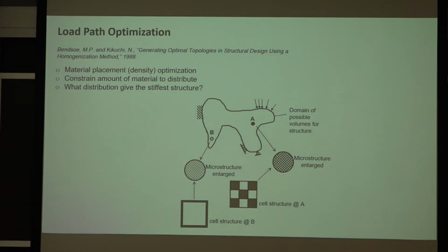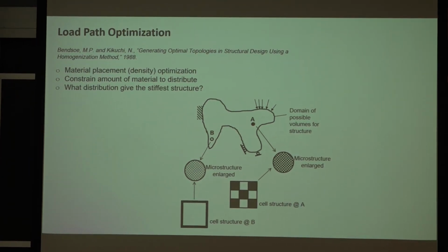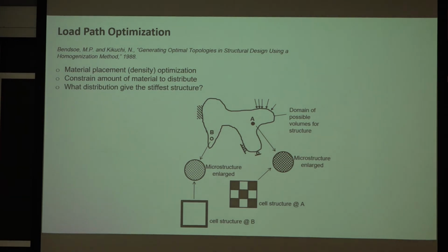You've got this crazy random shape. Okay, you're discretizing this into elements. Suppose I drew that better, right? And each of these elements is assigned a density. That density is now the design variable. The density can go between 0 and 1. So you're initially assigning a density to each of these elements, right? Suppose you've got 500 elements. What's your design space? How big is your design space? Page, you have it. 500, exactly. So you've got 500 variables now.